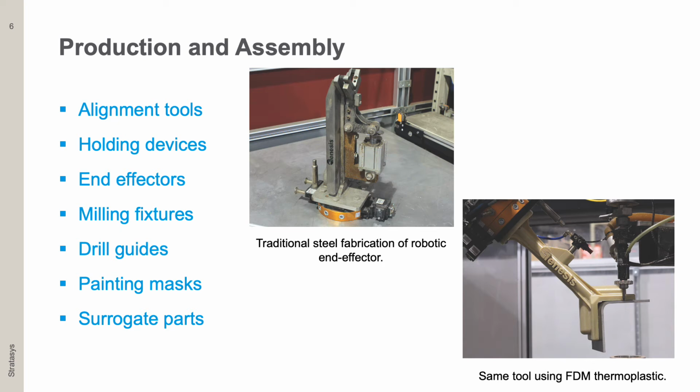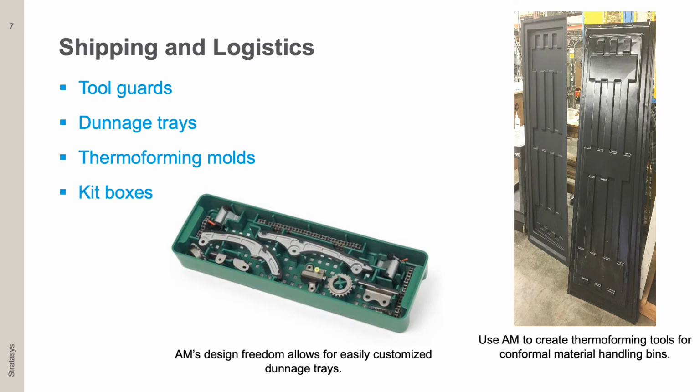This is just one example of how FDM technology provides real benefit in the jigs, fixtures, and tooling space. Sometimes overlooked, but just as important, are manufacturing aids that help organize parts and tools as well as transport parts through the production process. This includes bins, trays, racks, and assorted devices that maintain organization. Making these items with AM affords the design freedom to easily customize them to the part or tools they carry. The design freedom of additive manufacturing makes complex designs possible where an equivalent machine tool would be too time-consuming, expensive, or even impossible to make.